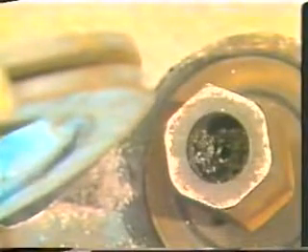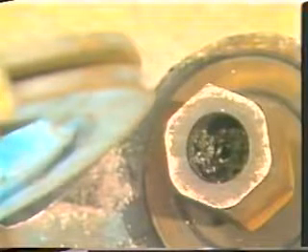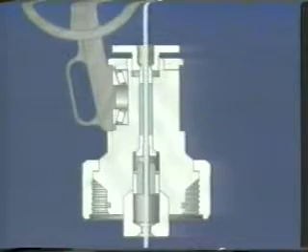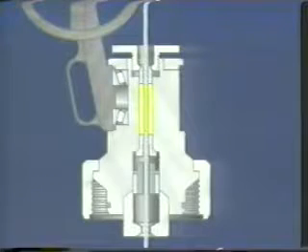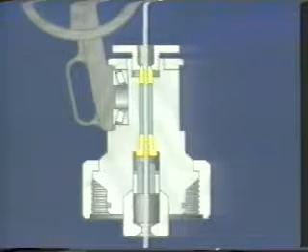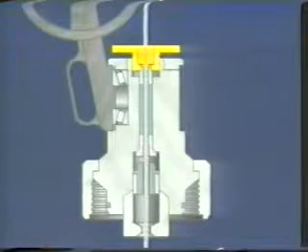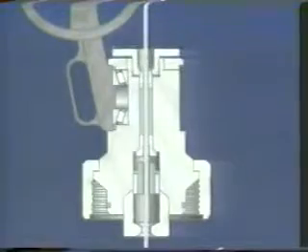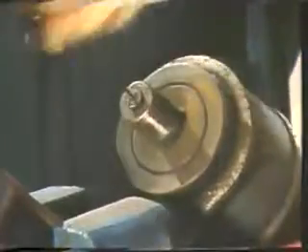The stuffing box seals around the wire line and allows the tools to be run into the well with no loss of well fluids. Inside the stuffing box, the packing is held in place by two glands, one below the packing and one above. The gland above the packing is held in place by an adjustable packing nut so that the packing can be compressed to expand it against the wire. The packing segments are small cylindrical-shaped pieces of rubber or some other elastomer with a hole through the middle.